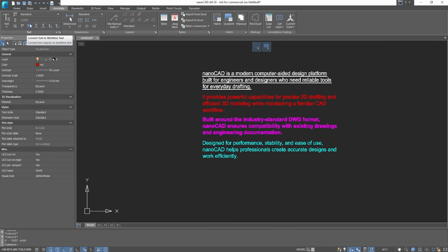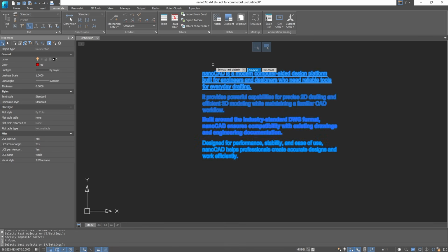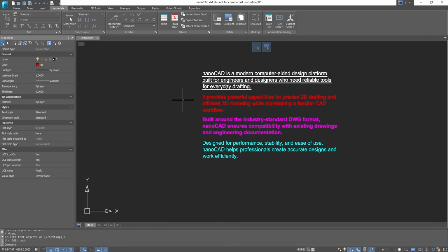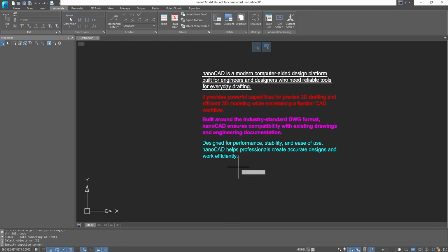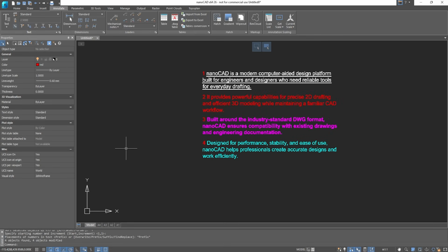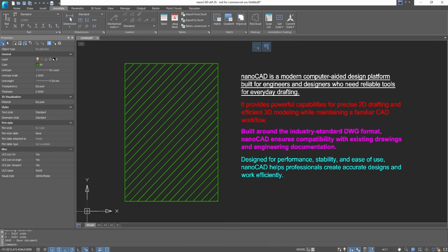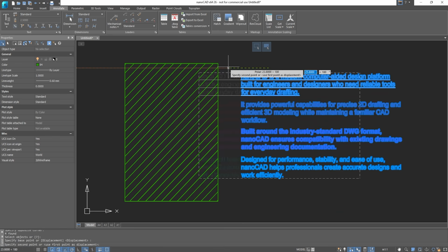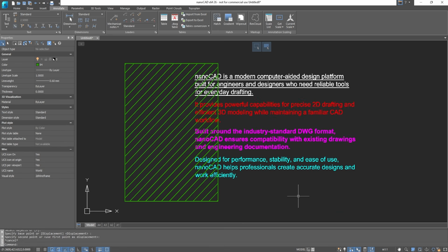Text to Multiline Text Conversion merges multiple text objects into a single multiline text for easier editing. Auto-numbering automatically numbers text objects based on defined parameters. Text Mask and Unmask applies or removes background masking to prevent overlap with hatches and drawing geometry.